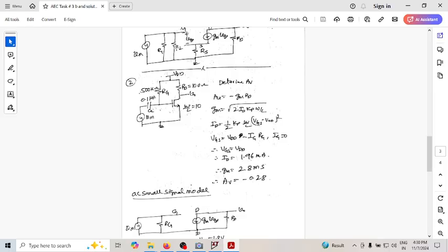So when R2 is less, let us make the value of R2 so large that when it is in parallel with R1 it should yield 25 kilo ohm. So how large should I keep it? If I keep R2, which is the smaller quantity among these two, at twice the minimum, twice the Rin required, then your Rin can never be less than 25 kilo ohm.